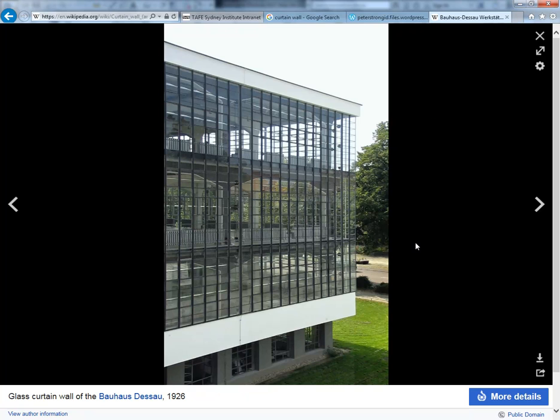Looks stone, it is stone veneer, but it's the same principle as this. It's a non-structural wall that wraps the building, and it's got I think a steel frame with the veneer applied to it, and so they're panels that have a steel structure behind it, and that's what supports the building. And it's the only way they could have built that because the footprint would have been totally taken up by the walls if they built it the traditional way, which was to have really thick walls on the lower levels, getting narrower as it went up.